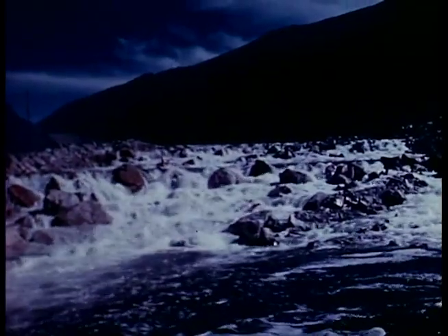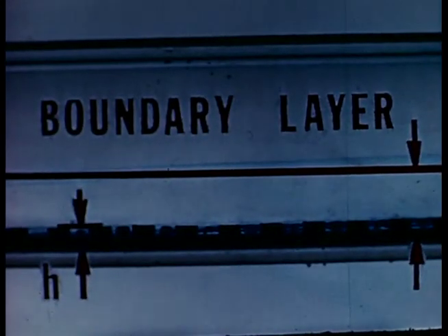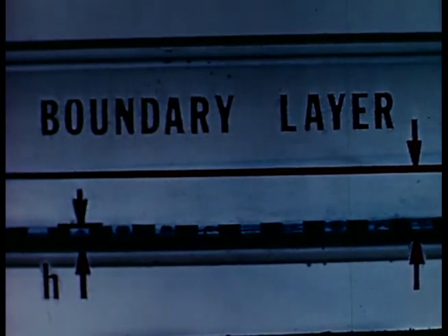Important characteristics include the size, spacing, shapes, and uniformity of the individual particles. These characteristics are usually represented by a single linear dimension called the equivalent roughness height, H. H is often measured with respect to the boundary layer thickness. It is not always equal to particle height, as shown here.